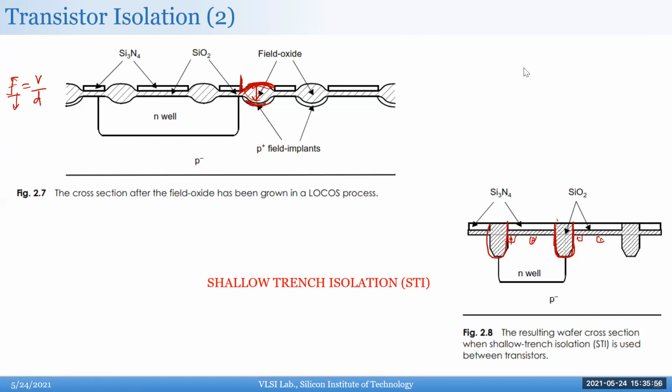Oh, what is the function of Si3N4? That is just the way they do the shallow trench isolation. So that's a silicon nitride they use. I don't know exactly why they use it, but you can look it up. But that's what they use for shallow trench isolation. Essentially, the idea of the shallow trench isolation is that you still have a resistive path, but now it's a longer resistive path to connect between two diodes.